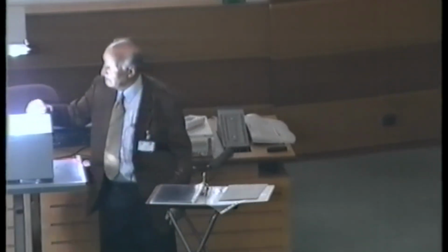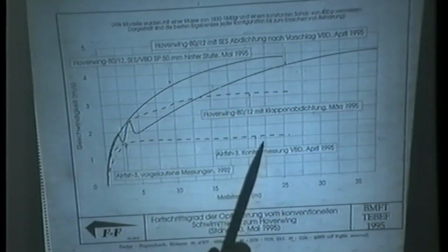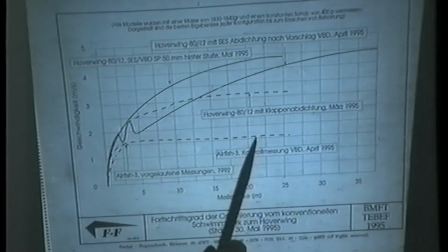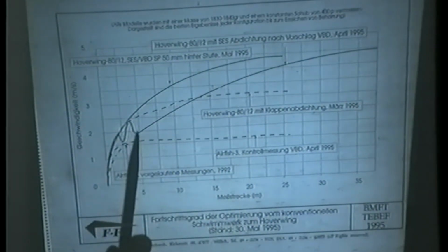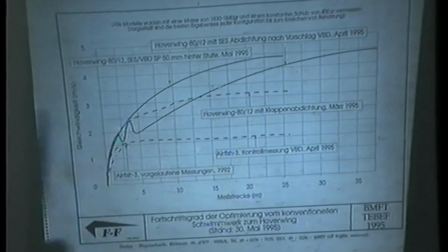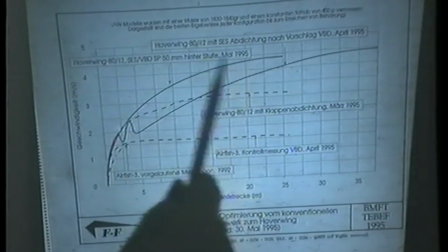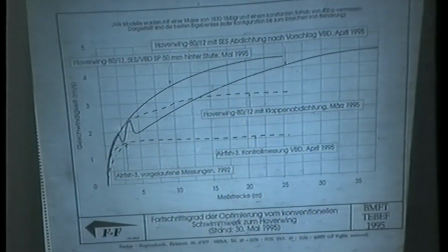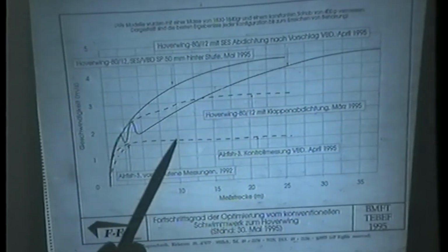You see here, this model ended up at 2.5 meters per second, and then it was constant. Thrust was equal to drag. And then we tried with our static air cushion, again same weight, same model, same power, but with the air cushion. We came up to this speed, and after some modifications, which is easily possible with such a system when you run in the tow tank, we were able to double the speed. And this was the key point where we said, okay, this makes sense, let's build bigger craft.